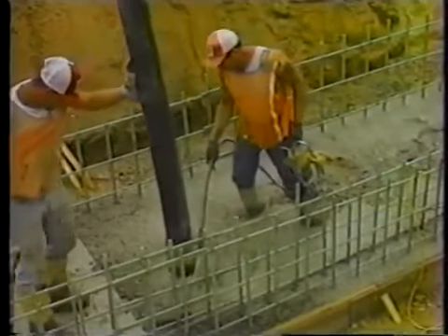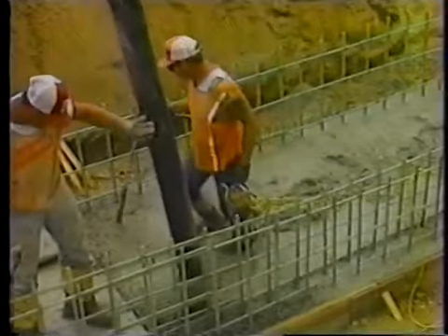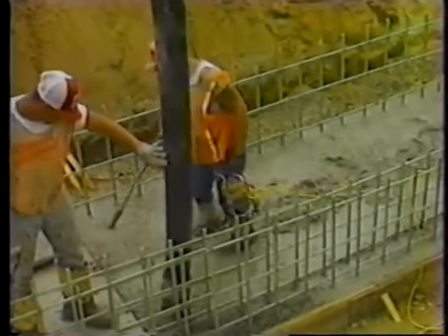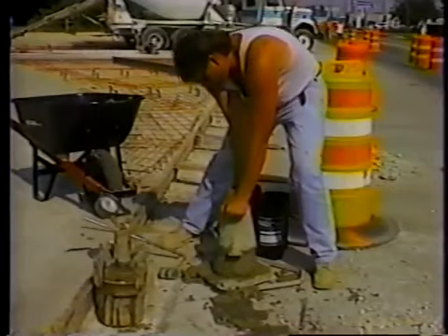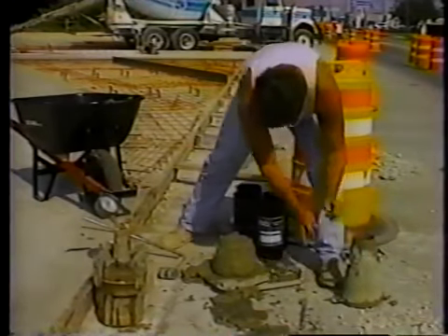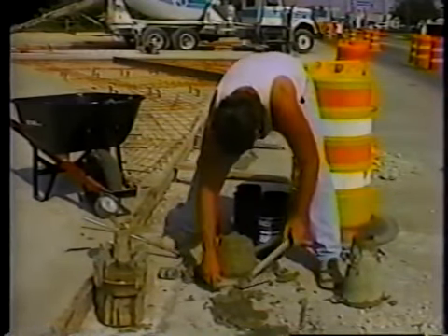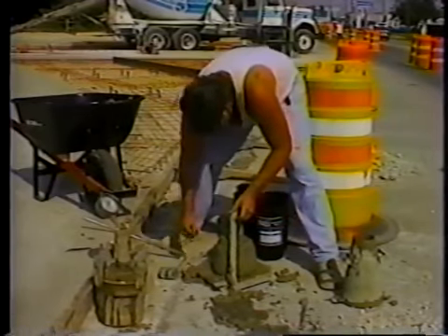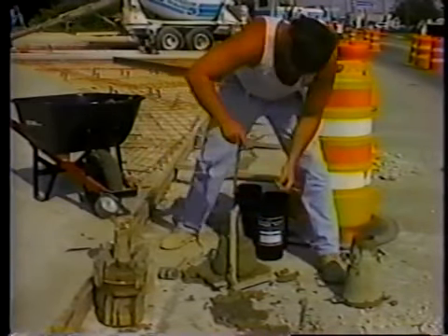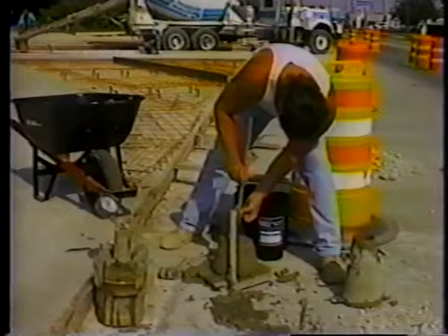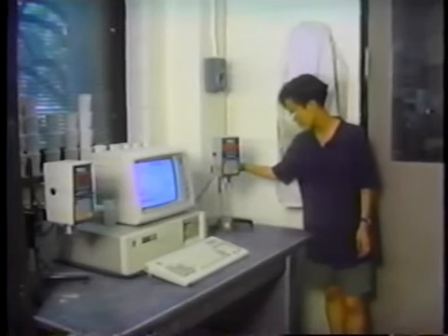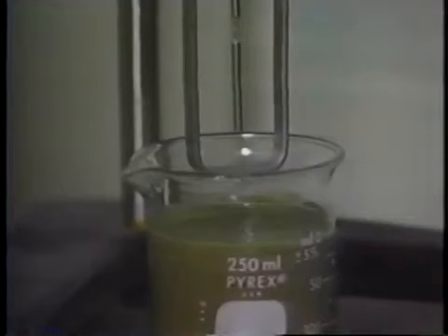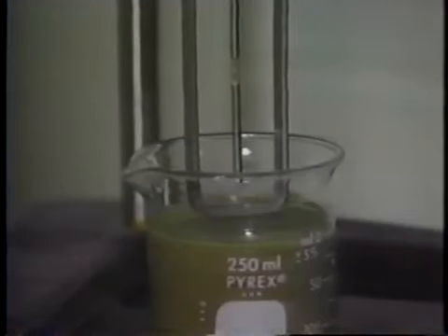The fluid properties of concrete are very important in the field because quality construction demands adequate consolidation. The standard slump test provides a coarse measure of concrete workability. This test is widely utilized because it is easy to conduct in the field. Fluid properties are also the subject of research in the lab because the flow of cement changes as hydration proceeds.